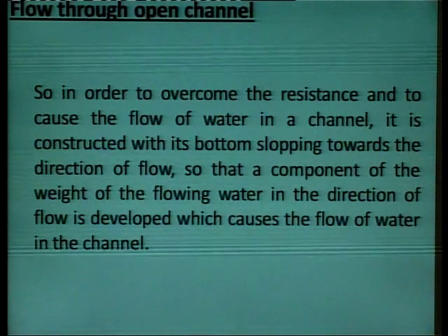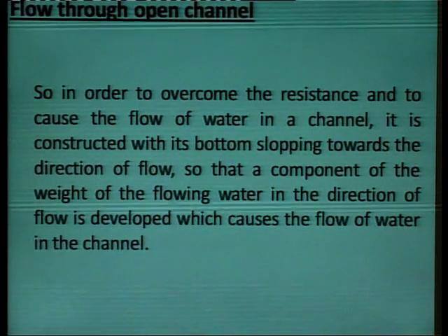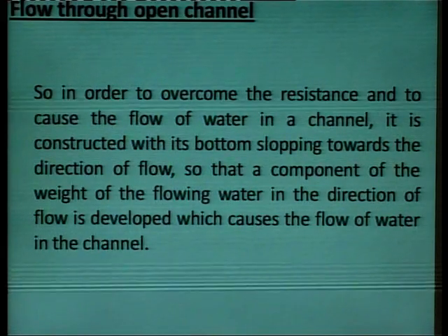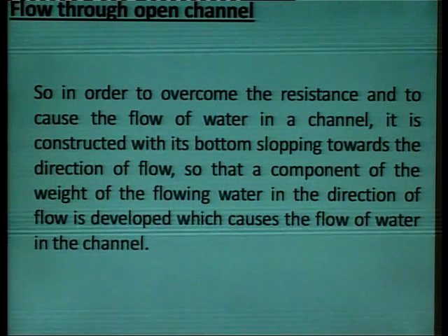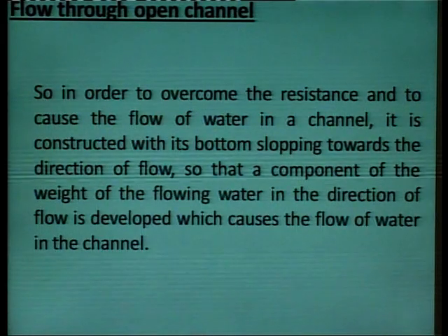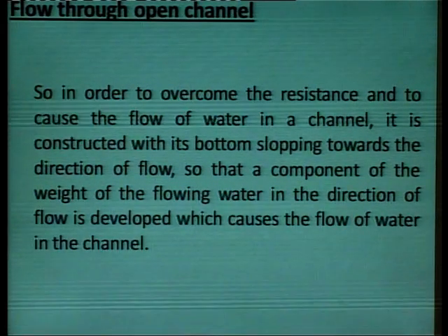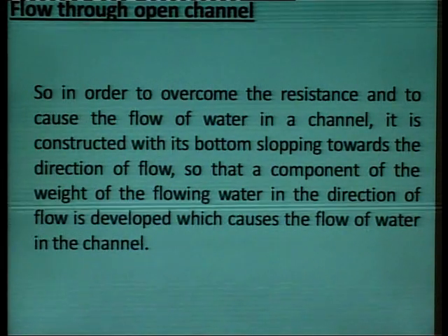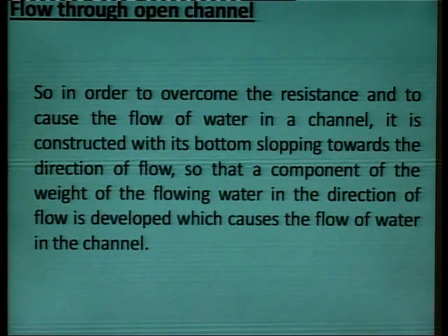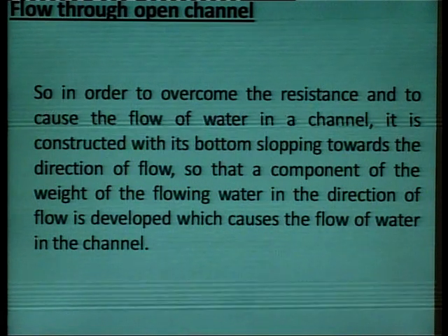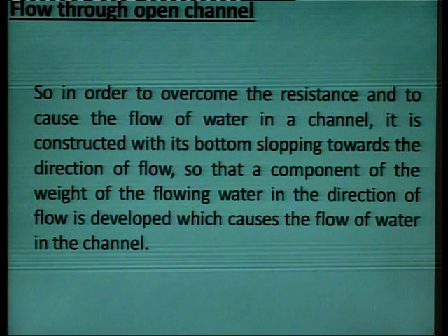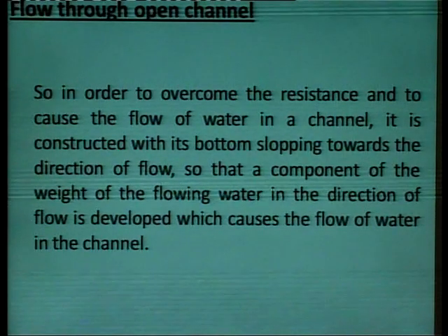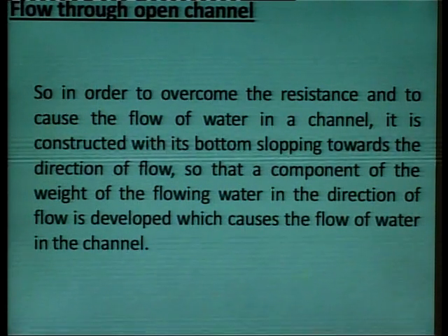So, in order to overcome resistance and to cause the flow of water in a channel, it is constructed with its bottom sloping towards the direction of the flow, so that a component of the weight of the flowing water in the direction of the flow is developed, which causes the flow of the water in the channel.